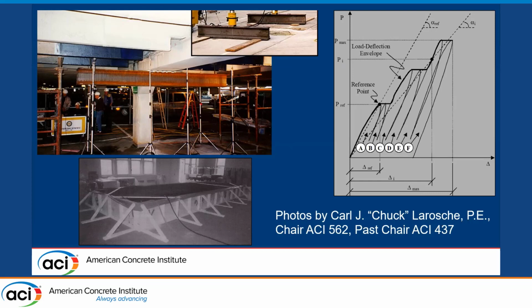But jacking is generally a more modern technique where you have these little posts or have measuring techniques, but everything is shored. So you see it being shored up to maybe an inch within the structure above. So if it starts deflecting more than you want, you catch it. Very, very safety oriented. And then you can run a couple of different techniques.